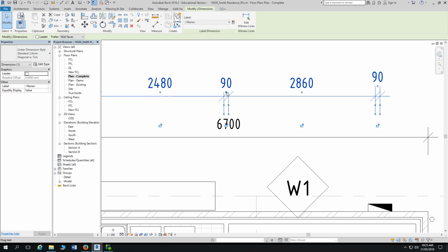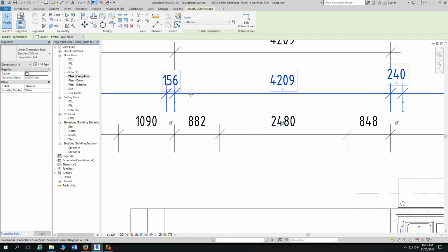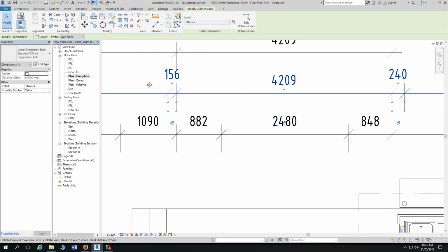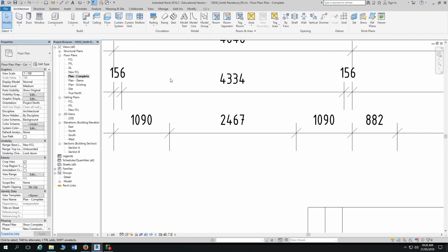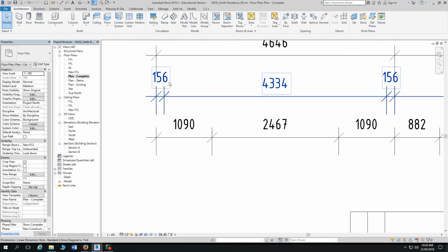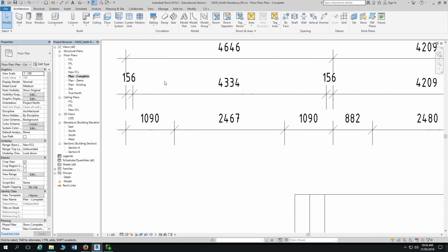The next one, when you push it up, will lock into the same height as that one, as will this one and these. So it's just important to move these up to get them away from these witness line extensions, make them more central, and make them readable.